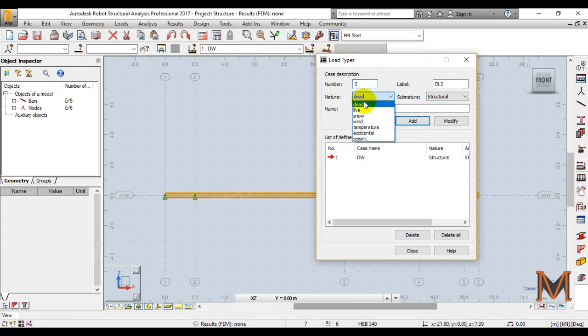The second load is going to be a live load. I'll call it live, and live. And for those of offices, was it category what? B, C, do you know? C. You can choose its category C. You can also not choose any category if you are defining your combinations by yourself. This category matters because now you will see we will define the load combinations.